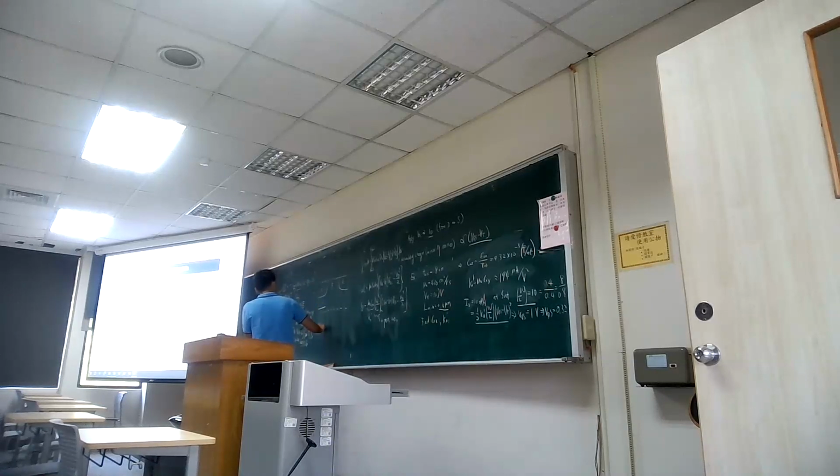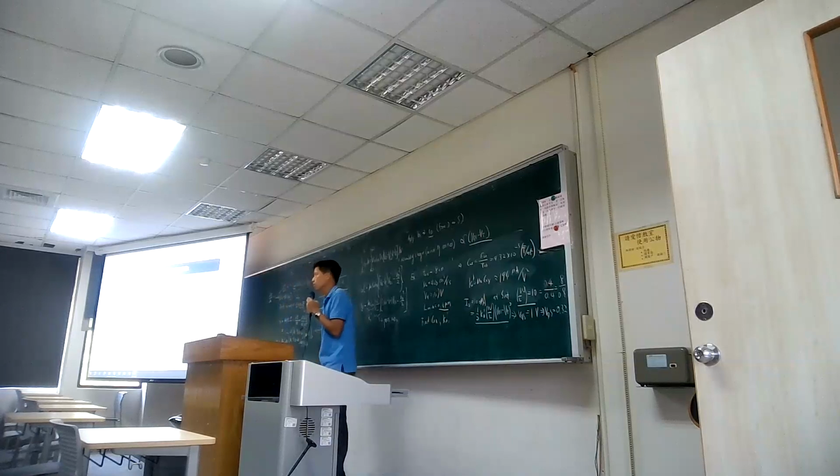So what is the N-type semiconductor? That means your Fermi level is close to the conduction band. So with the same material, that means you get the same band gap, 1.1 electron volt. And then in the P-type system, there will be a depletion region. So it is in the P-type region. And then later on, you will go to the N-type one. And how much difference in level? It could be symmetrical, but if you have different doping, maybe it's not symmetrical, depending on how much doping you have.